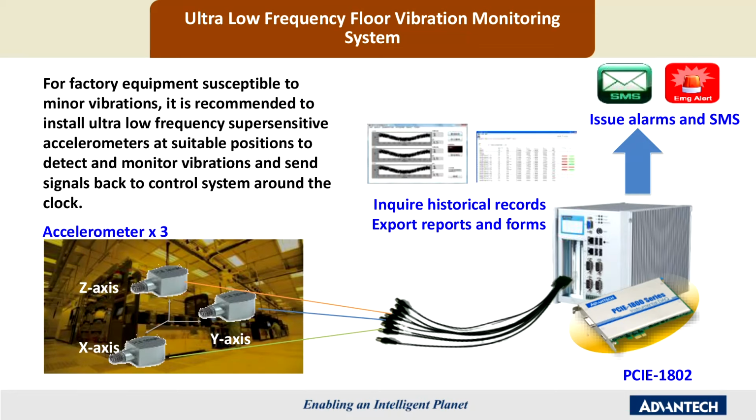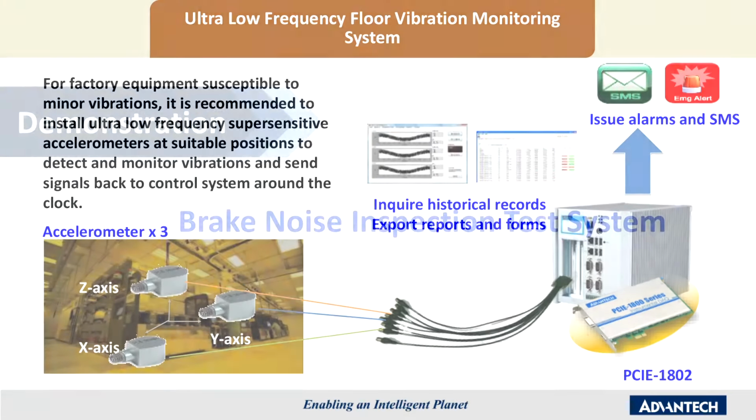In order to prevent micro vibration, it is commonly recommended to install an ultra-low frequency and super-sensitive accelerometer at a defined location to detect and monitor vibration all the time, and send monitoring data back to the control room management system. The PCIe-1802 with an embedded PC is the dynamic signal acquisition system, able to connect with several accelerometers, and a collaboration with a domain-focused partner provides these solutions.